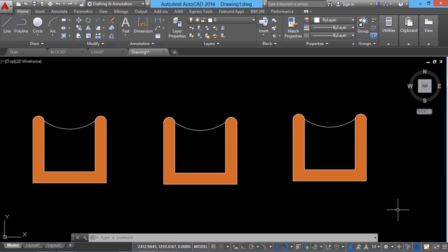This clearly indicates the fact that you can insert any other drawing into your drawing. But to create that external drawing, you don't have to go through all these procedures of making a local block and then using the wblock command to create the external drawing. This procedure is not always necessary. Whenever you want to make a block that is to be inserted in all the drawings, you can straight away make that drawing, save it with a proper name and in a proper location, and later on, using the browse option of the insert command, you can insert it in any other drawing.